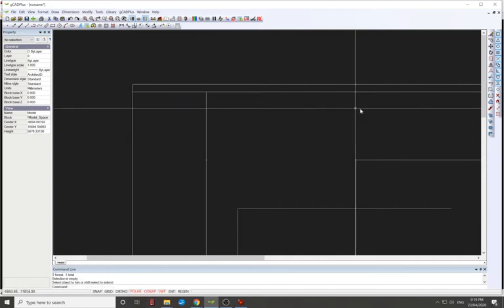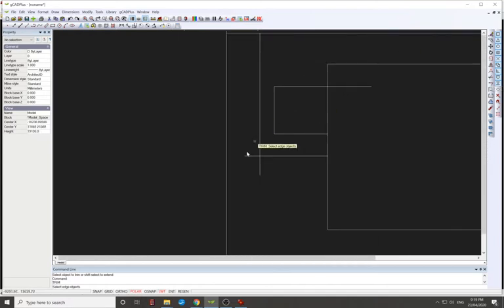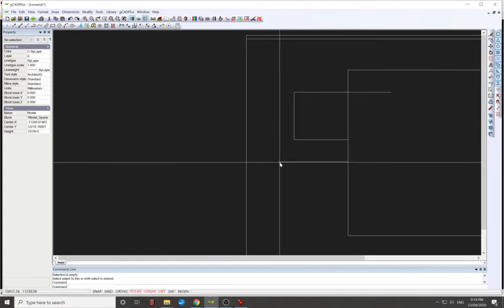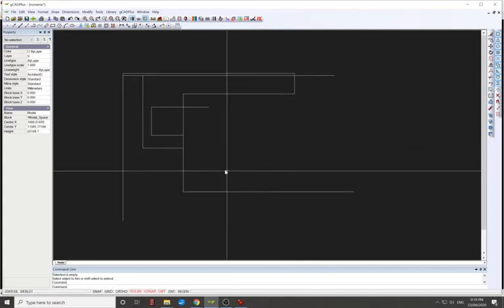And then you can just press enter, have the trim tool again. Say here, we want to cut to this line, we'll cut that off, we'll cut that to this. So you left click on that, right click, trim. You can't trim that one because you selected it, so you've got to unselect, press enter again for the trim, select this one, right click, and then cut with the left. Make sense? It's clear as mud. I will do it when so trim.